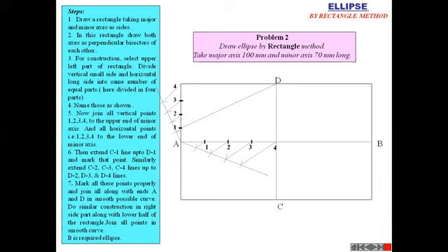Then join 1 to D, and join C through the point 1 on the line, to get the first intersection point. Second, join 2 to D and join C through 2 with an inclined line, and we get the second intersection point. Similarly join 3 to D, then C through 3, and at the intersection we get the third point. Then the curve is completed here.